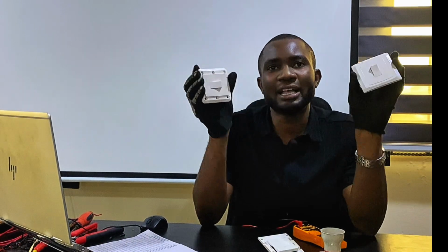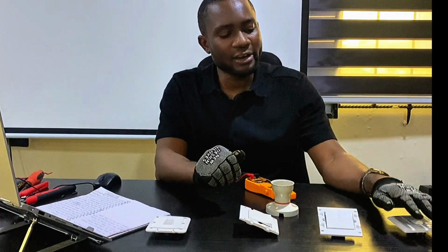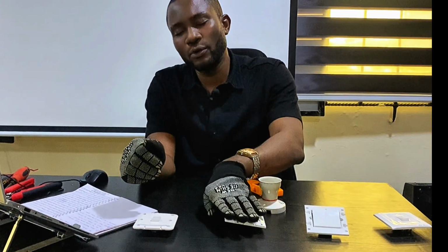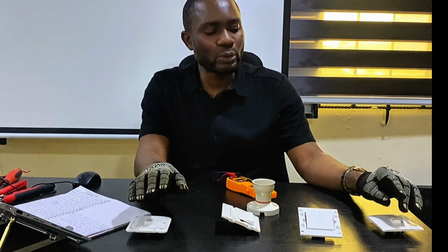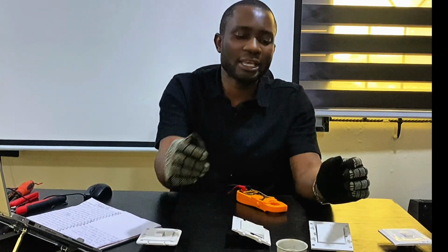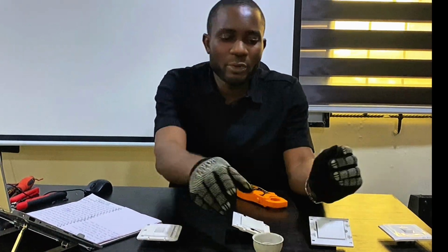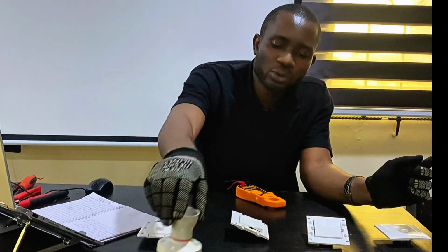So what we want to do, like for your staircase, let's assume that we have 3 floors. So this two-way switch that we have is going to be at the ground floor and the last floor. So we have this at the ground floor, we have this at the 3rd floor, while you have this at the 1st floor, we have this at the 2nd floor. So these are ground floor, these are 1st floor, this 2nd floor, and this 3rd floor. You want a situation whereby this lamp is on the staircase, and you can have as many lamps as possible. Maybe you have 1 lamp at the ground floor, 2nd floor, 3rd floor, as many lamps as possible. You loop them in parallel.